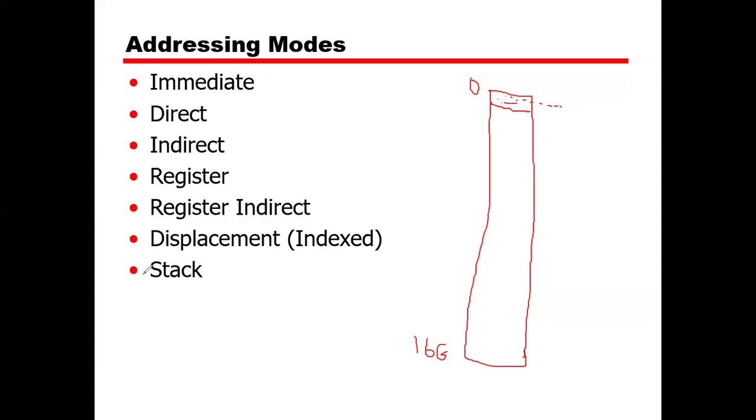Okay. If I'm building an instruction set, guys, and you know, building an instruction set goes with opcode first, and then operand, and address. I can have more than one here. It doesn't matter. The question is, how many bits you will, or you need, or you want to allocate to the address, guys? This is very important. How many bits you want to allocate to this address? Okay. If you want to say, for example, load, this is an opcode, this is an operand.